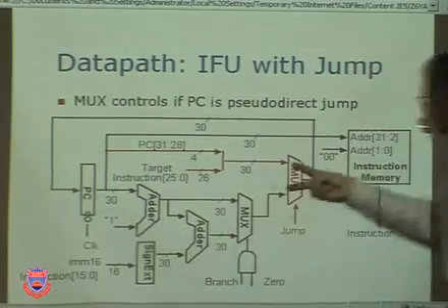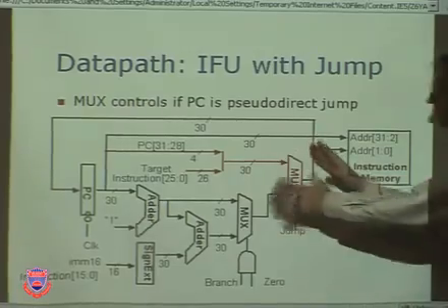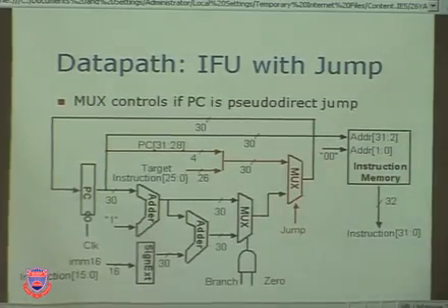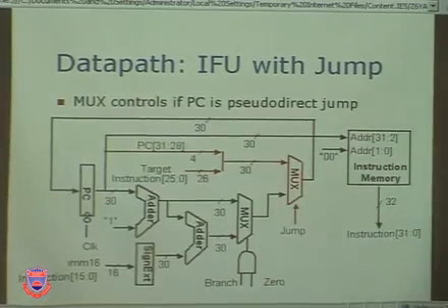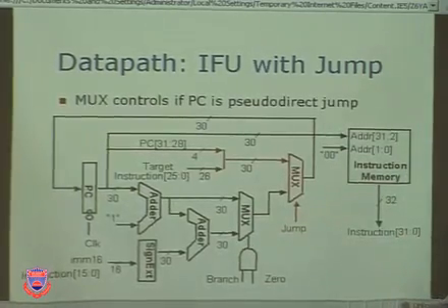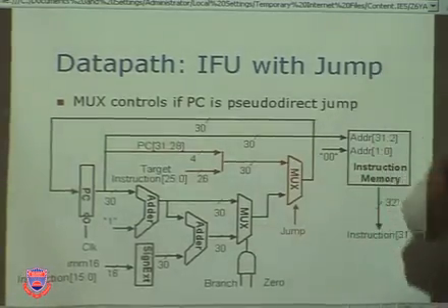Okay, so there we go, a 3-to-1 MUX combination. It could be done with a single 3-to-1 MUX. It's shown here just for simplicity as 2 sequential MUXs. This is actually not very fast. This is going to be 2 levels of delay, 2 levels of delay, grand total 4 levels of delay. We could certainly do it better with a single MUX with 2 levels of delay, couldn't we?